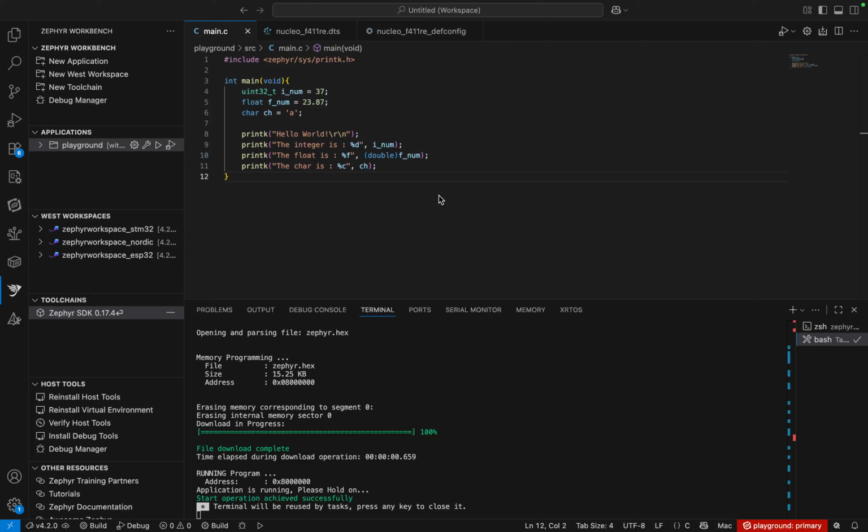I'm mentioning this because it's easy for you to assume that because you connect one side of your MCU to the USB cable and the other side of the USB connector goes to your computer, it's easier for you to mistakenly assume that there is a UART USB connection. That is not always the case. Sometimes the USB cable is just for uploading firmware onto your board.